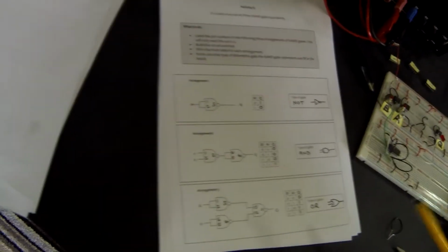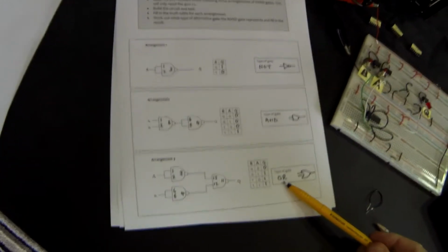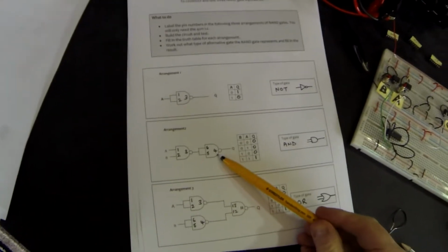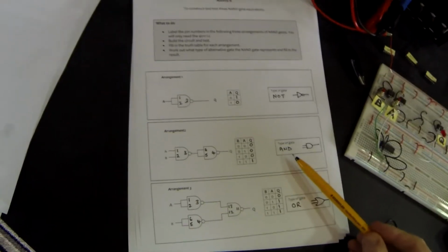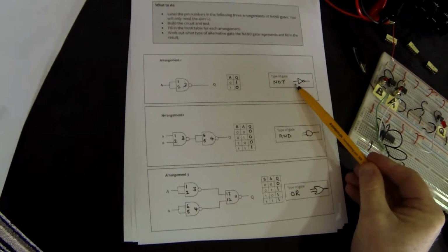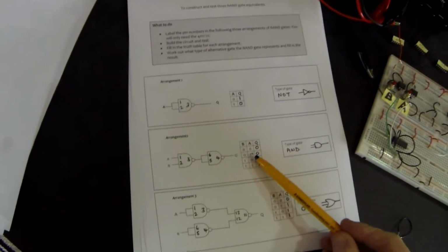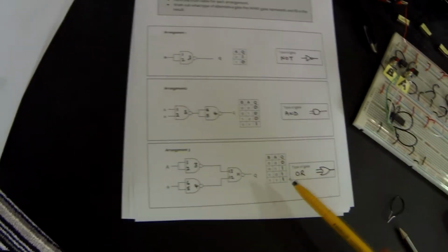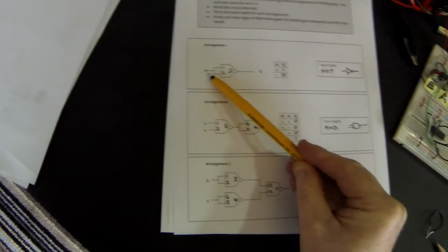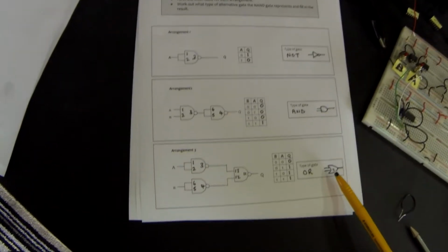So, what can we conclude from NAND gate equivalence? Well, at the moment we have a NOT gate, an AND gate and an OR gate. This was not a NAND gate, which made it an AND gate. If I were to put this NOT gate onto the end of this AND gate, I would give myself a NAND gate. If I took this NOT gate and put it at the end of the OR gate, so the one input here from the one output here, I would turn it into not an OR gate, so I would turn it into a NOR gate.